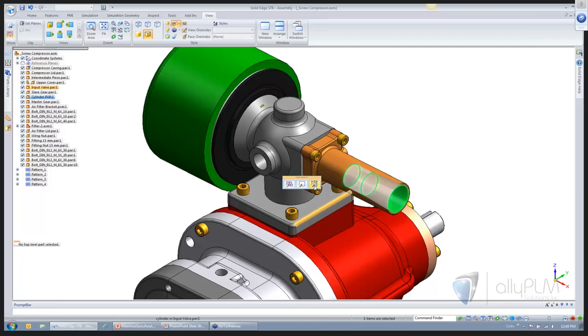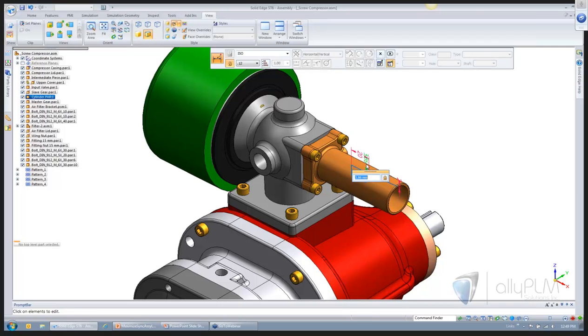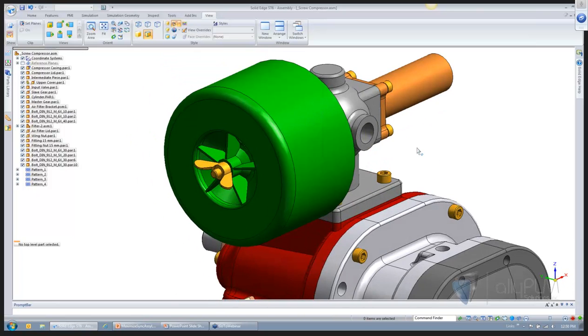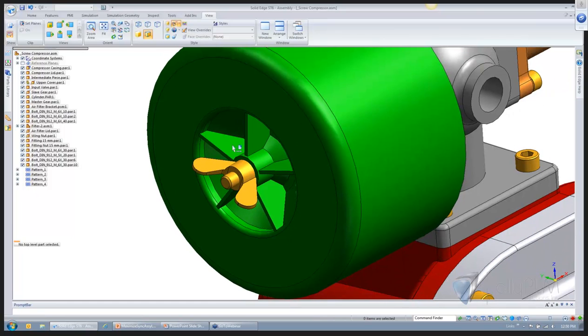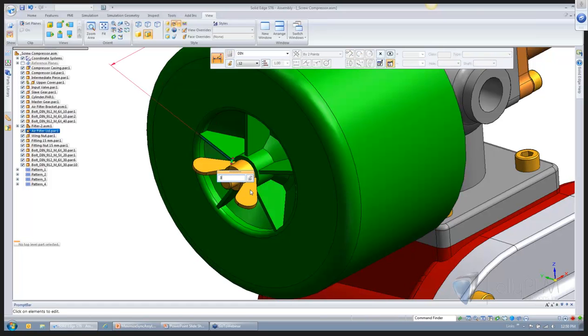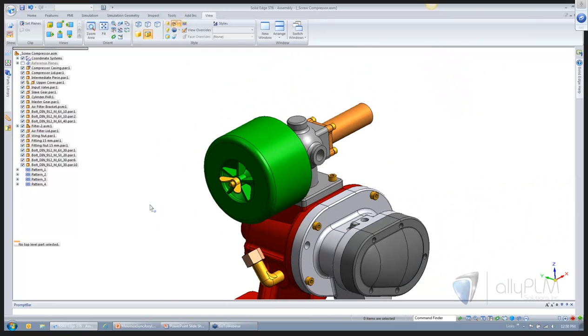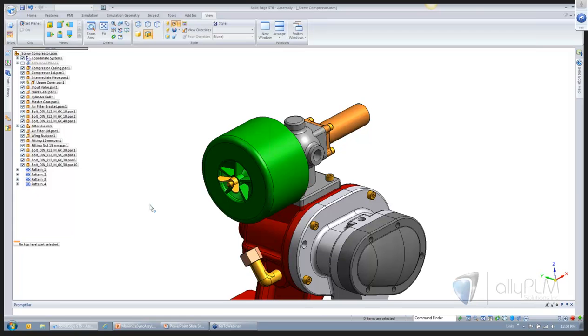This is something new. We have to be in face priority mode, and when we select ordered faces, we will infer their feature set, and we're going to expose the dimensions that are given to those, and then we can make modifications. The same is true on this side where this rib and pattern is. If I select this face, the face actually exposes the feature, and then I can expose the dimensions to that, and I can modify this rib pattern feature of an ordered part by using synchronous assembly modeling.